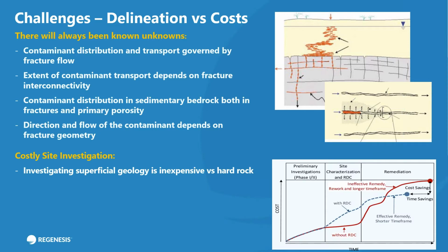With these hard rock sites, your site investigation and drilling is going to be costly. So when it comes to planning this, you want to make sure that every well on your site is working as hard as possible for you, so you can better not only delineate and understand the conceptual site model, but also take the opportunity to use this infrastructure as part of your remediation strategy.